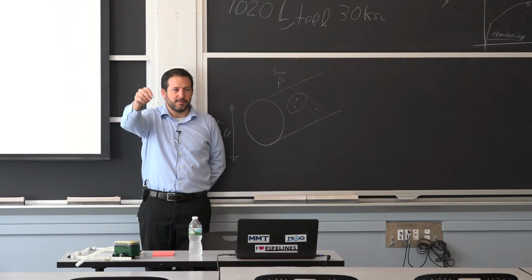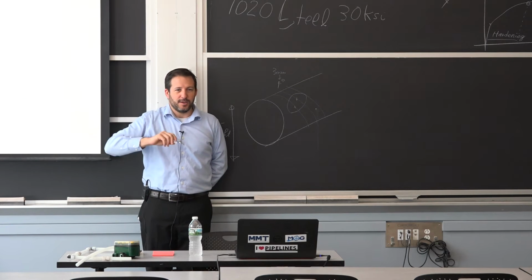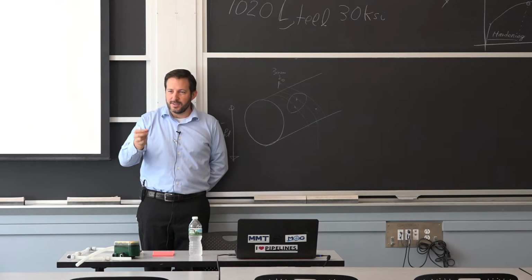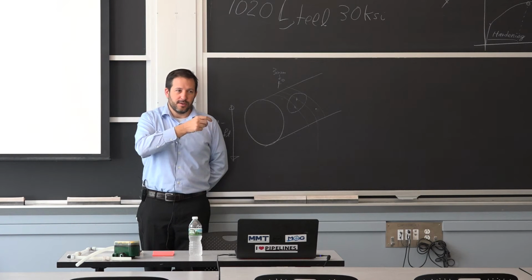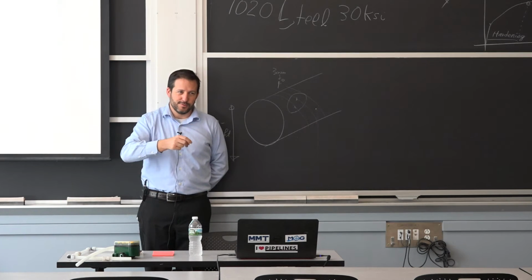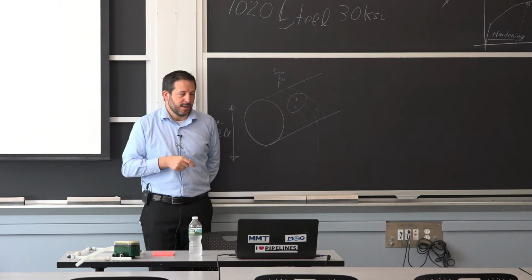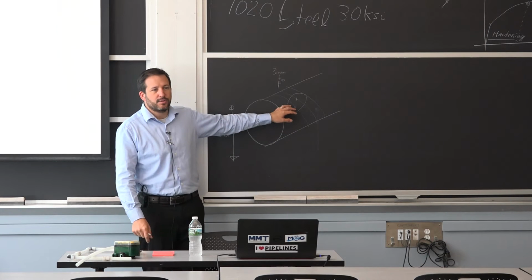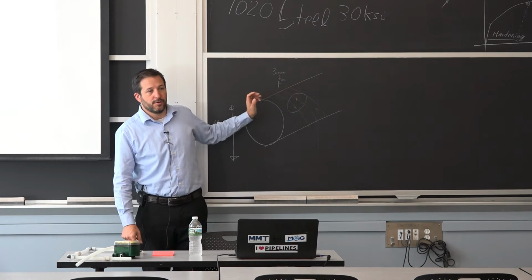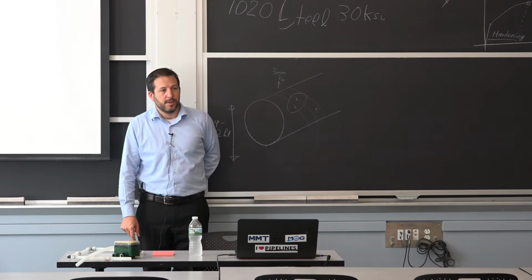So they have sensors every 10 miles around the line with data acquisition, and when they hear an indication, they say, okay, there's a wire that snapped, okay, there's another wire that snapped, so then they try to infer where it happened so they can be proactive before there's actually a real failure. They locate the area and come and repair it.